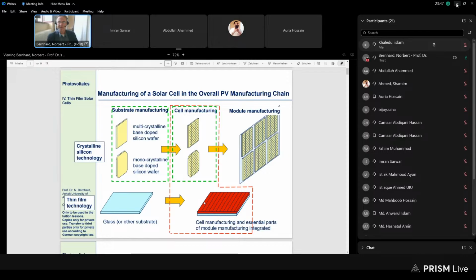And this is easily reached by these three patterning steps. And I said already in the first picture that usually it's an ablative laser scribe. This is true at least for cadmium telluride and for amorphous silicon, but partially it's also mechanical scribing. I mean, this is in case of step 2 and 3 in the copper indium gallium diselenide technology. The reason is just that in this technology, the laser, which of course in general is the preferred tool, does not work so well, and therefore usually one still uses mechanical scribes there.